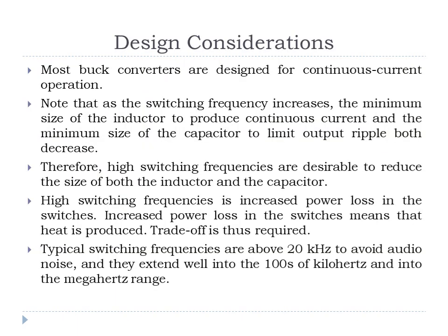So as we conclude the design consideration of buck converter, the design which we have discussed is the continuous current mode operation. Switching frequency is one of the important parameters, because if the switching frequency is high, a low value of inductor and capacitor would be required in the circuit. Particularly in case of inductor, because inductor is a bulky component, usually a high value of switching frequency is opted, but as switching frequency increases, the power loss in the circuit also increases.